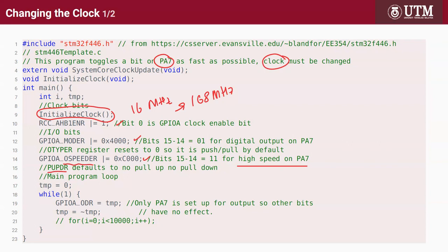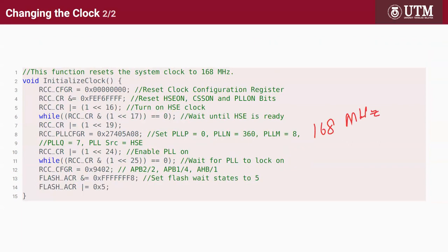And then here we just toggle, with no delay. So send high or low as soon as possible. This is the fastest loop that we can get. It's also possible that STM Cube does this too, and we don't normally care. When you use STM Cube MX, it will do a lot of configuration and put in the function.